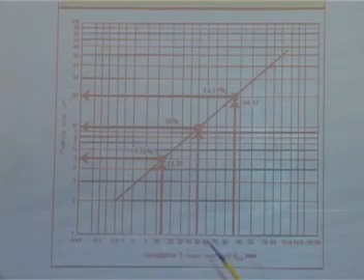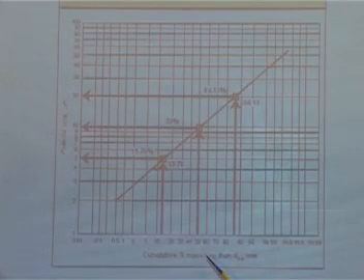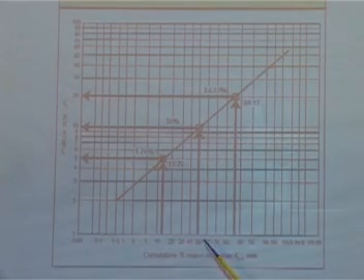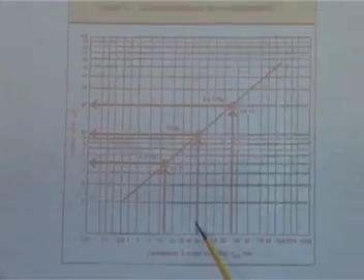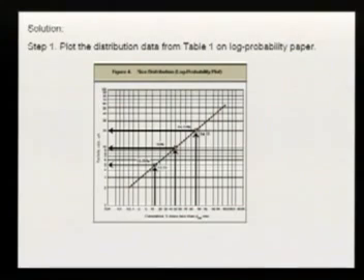And what you can do is look at the 50%, D50, where 50% of the mass is there, and that will be your geometric mean diameter. You can find it out. So the particle size of 10 micron is the geometric mean, and then if you go to 15.78 and 84.13, you will get the value of the standard deviation. Do you know why it is the standard deviation? Let me also recall here.